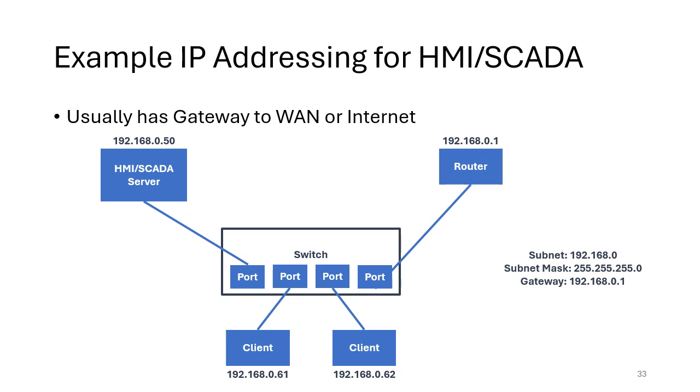It's not a huge amount. In fact, it's probably negligible, but it needs to be considered in high performance networks. It also means you need more powerful devices, and that's typically why PLCs and I/O don't support DHCP. It's because they don't have the power to do that. Having said that, I've used quite a few modern I/O devices, and you can configure them for DHCP. They're powerful enough now that it could be done. But in the past, we just didn't have the computer power at that level to be able to do that.